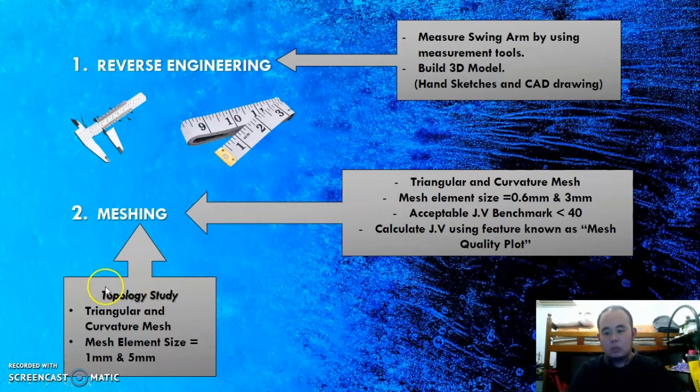And later during topology study, we create the mesh also with triangular and curvature mesh with a mesh element size of 1 mm and maximum at 5 mm.